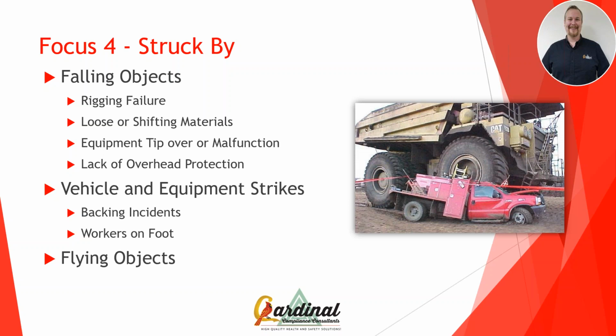And lack of overhead protection. I was speaking with a safety professional last year, and we were discussing a fatality in New York City. And so here's what happened. There was a hanging scaffold 10 stories up, and a support, just a little angle support, fell 10 stories. And the first question that safety professional had was, well, why wasn't he wearing his hard hat? Now, I hate to say it to anybody who's relying on that hard hat to save you, but let me point this out. That scaffold bracket was about 5 to 8 pounds, give or take. It fell 10 stories at that point.